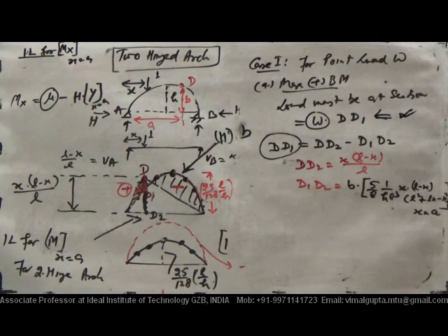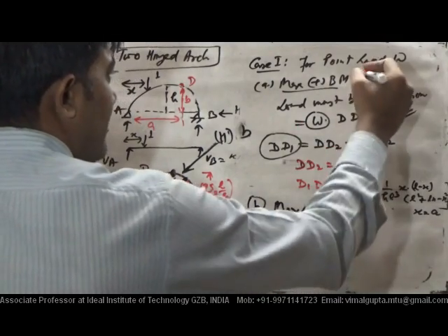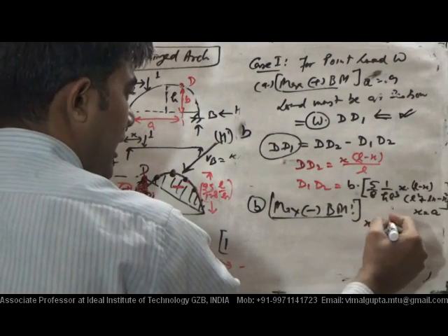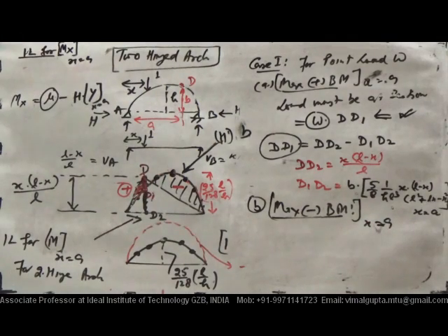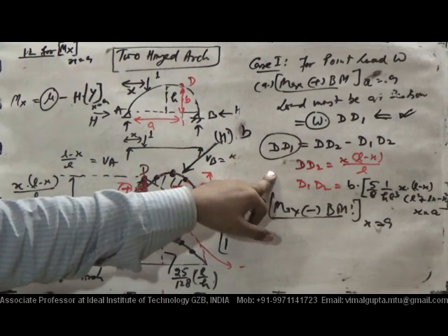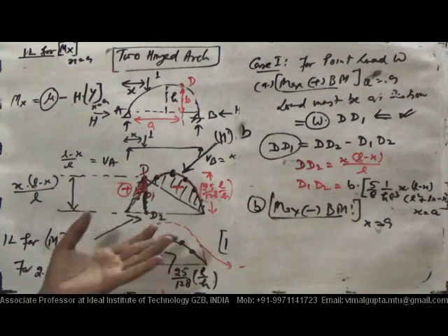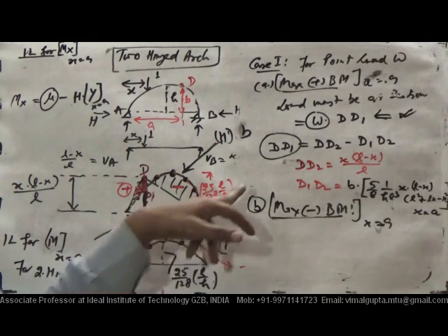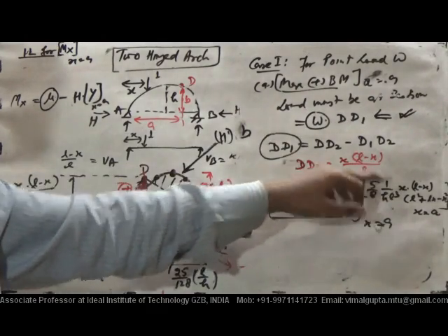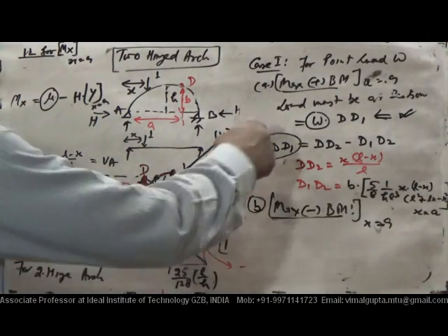Okay. Now, if maximum negative bending moment is required at any section x, I am talking here about any section A. Okay, at any section, I am not talking about absolute. Here, if the absolute value is required, you know very well absolute value is free from the section. It means you also have to locate a section where that maximum value can be possible. So after having the expression in terms of this, differentiate it and find that value. It basically involves multiple algebraic calculations.